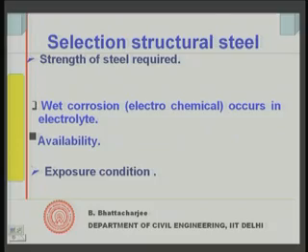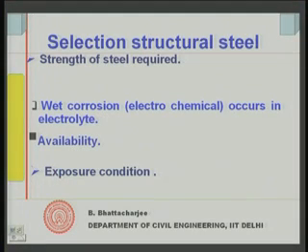protection against corrosion, etc. Which steel is available? Supposing a steel is not available, you can't use it. So, availability will be one of the major factors which will govern what our requirement is, what steel I am going to use. Exposure condition would decide again what steel I should use, because if it is a highly corrosive, aggressive environment, then you have to choose steel accordingly. So, that is, and mechanical properties overall.